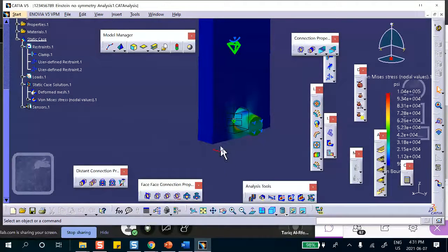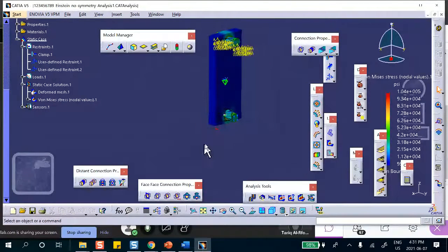Okay? As I said, it's going to give you color and numbers and things like that, but it's simply wrong. So if you use the edge or if you use the face, you still need 1 point to avoid rigid body motion. Talk to me afterwards. We can go through it if it's still not a convincing argument that I'm giving you, okay? Are we good?